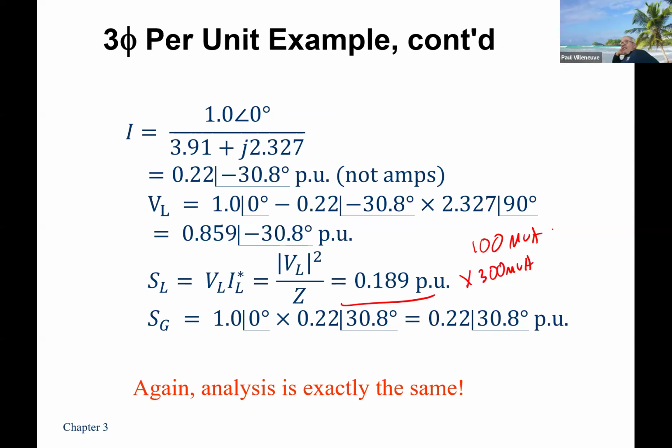What about our mechanical engineering friends? Do they care that that motor has a single phase output of 33.3? Or do they really care what's on the shaft, what's available for power? There's only one shaft, isn't there? Last time I checked, they don't make motors with 3 shafts. They make a motor with a single shaft. And that total mechanical equivalent power is 100 horsepower. Not 3 shafts putting out 33.3 each. So with our loads, we're always talking about a combined load. 100 MVA, 100 horsepower, et cetera. We don't care about single phase ones.